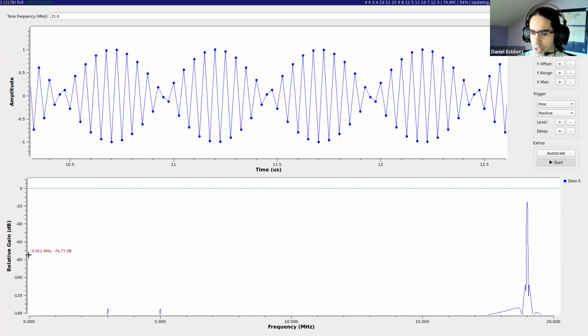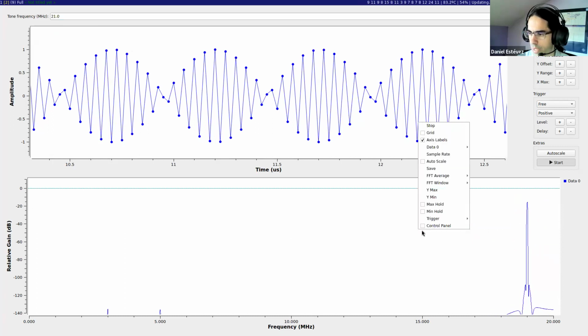We can imagine all the frequency axes going from 0, increasing, and it would increase all the way to infinity, going beyond the right side of my screen. But what happens when we have this 40 million per sample digital representation of the signal is that when we reach 20, we fold back. So instead of increasing, we decrease, and then 21 would be placed at 19 because going 1 megahertz up is now equivalent to going 1 megahertz down. 22 would be placed at 18, and so on. And if we go all the way up to 40, we can see that.